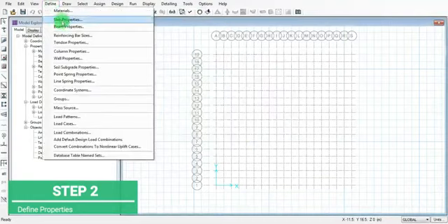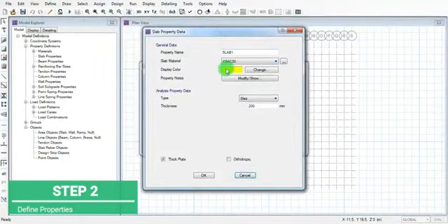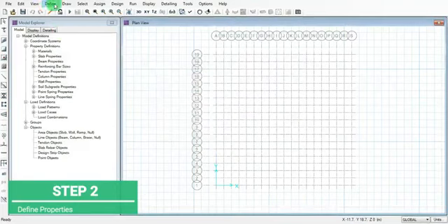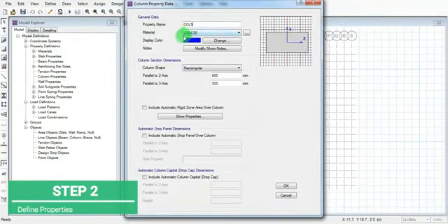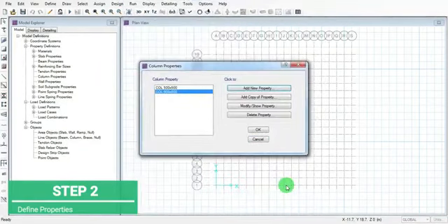Then go to Slab Property, add the slab property for the mat footing, which is M40. Add the thickness 500 mm. Click on OK. Then define the column property, add a new column, column 1. We have 2 columns, the first one 500 by 500. Add its sizes 500 by 500, click on OK. Then another column 600 by 600 and click on OK.